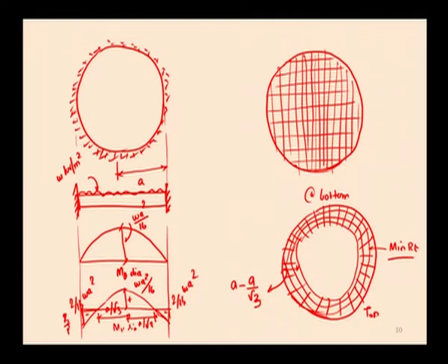A square. So, when you take the cross section of the slab which shows the reinforcement, this is fixed supported, and the bottom reinforcement we are providing along both directions, in the form of a mesh. So, this is the radial reinforcement, that is, radial moment or circumferential moment at the center, and this is the top reinforcement, this is the length of reinforcement, that is the radial reinforcement, and this is the circumferential reinforcement.